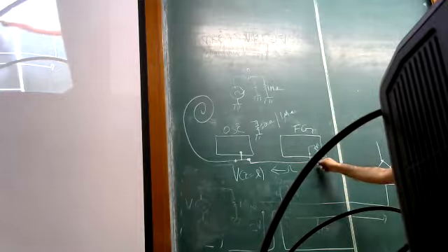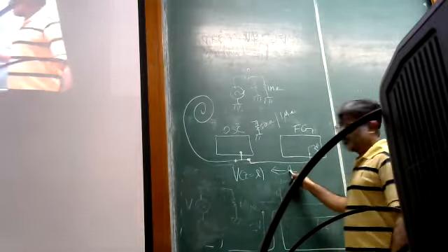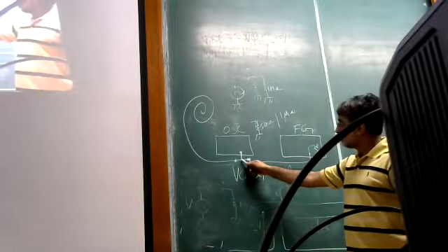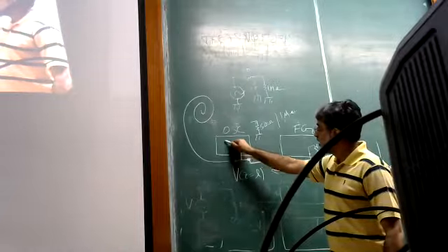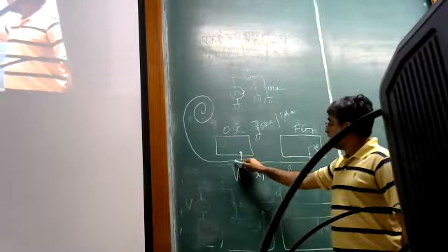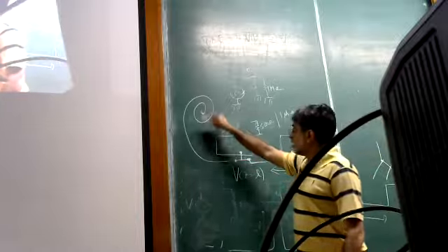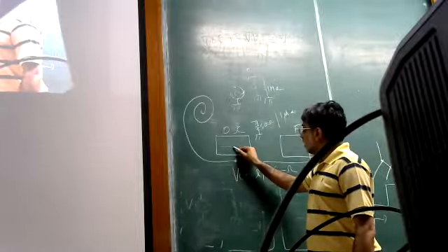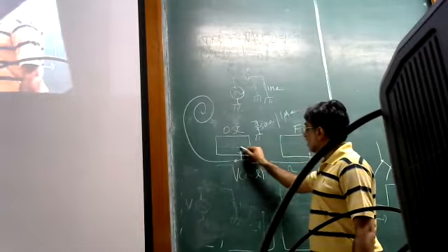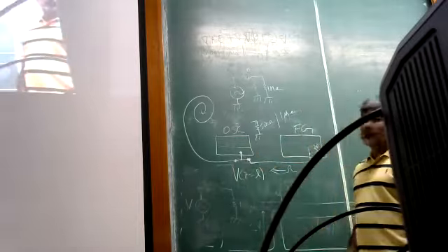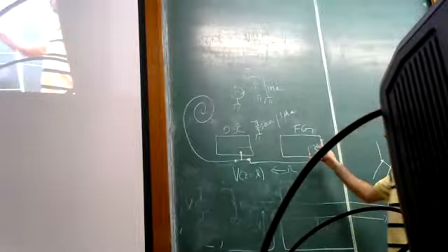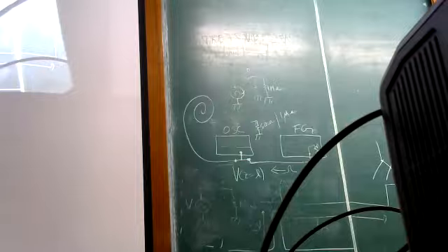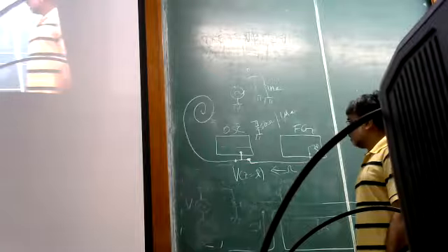The pulse travels from here, amplitude now half of what was before, measured here by the oscilloscope, which displays a pulse. This travels all the way, there's some time delay, and then you come back. And that's it. Some time much later a second pulse will come, but that's just because this is set to repeat itself at some rate.